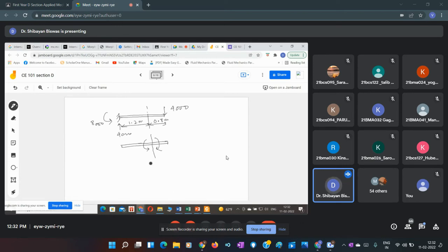We can also see that for both the parts, the value of the reactive bending moment is the same. So if we come from any part of the section, it will give us the equal bending moment value at that section. Both the parts will give us the same amount of bending moment at a particular section which we have considered. So what is the definition of bending moment? We can say it as BM also. Bending moment at a section, say YY.